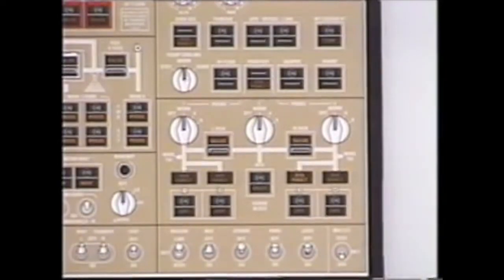Also note that the hydraulic reservoir head pressure receives pneumatic air from the respective wing manifold. On the center manifold, probably the most important thing as a flight crew member is the lower cargo fire detection system, aft cargo heat, with other items to include the number 2 pack, trim air, and potable water tank pressurization.